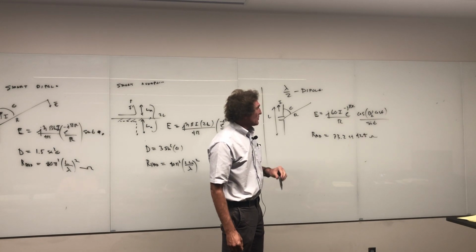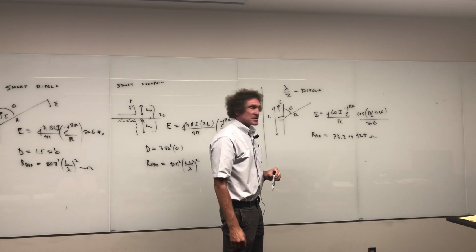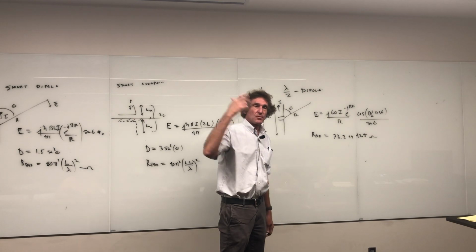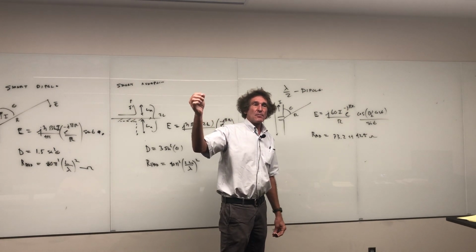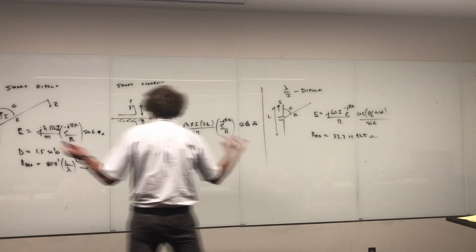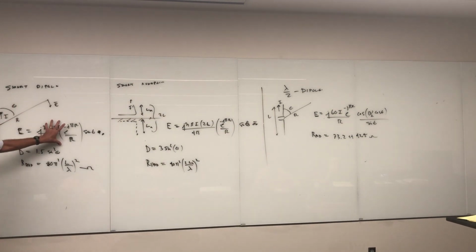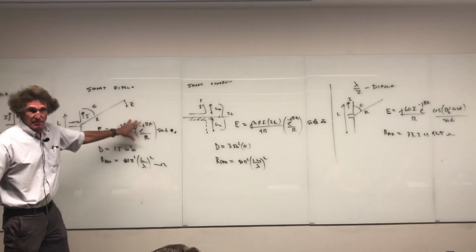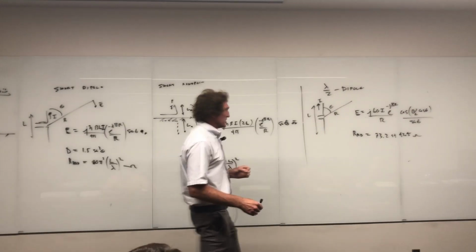It's cosine of pi over 2 cosine theta divided by sine theta. If you look in the book, it's the formula for the half-wave dipoles. And remember, Stu likes putting in the power. If you want the power for this, the only thing you do is take this, square it, right? The E field squared divided by 2 eta. I like the E field because that's usually what they measure. Typically, they sometimes measure power.